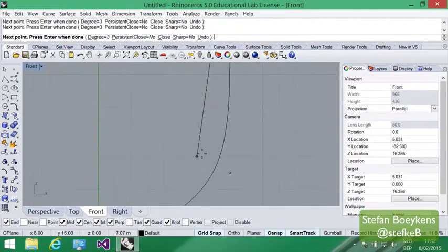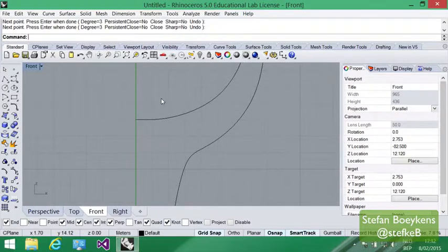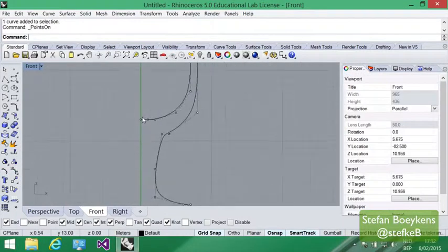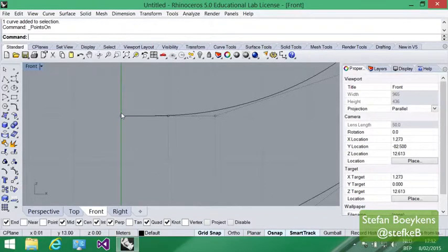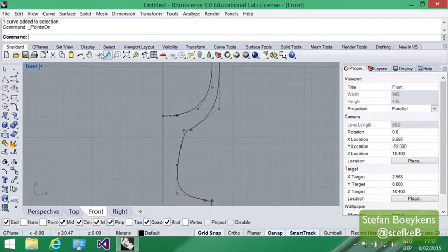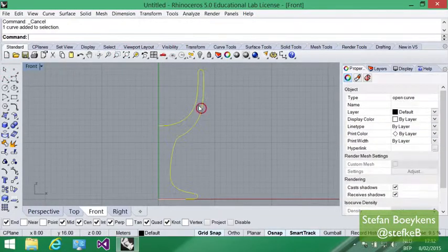We are not really concerned about the actual scale of the glass, but we want to ensure that we end up at the last position with 2 or even 3 points that are in the same direction. Enter. These additional control points, if we activate them, ensure that our last part of the shape is completely horizontal. Okay, let's zoom extends. So this is our shape.